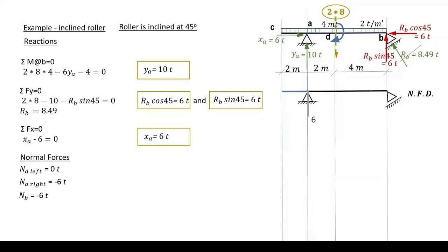And the closure here is this 6 tons, the red 6 tons, acting in an opposite direction, so we will rise and we will have a closed diagram which indicates that we computed all forces in the x direction correctly.